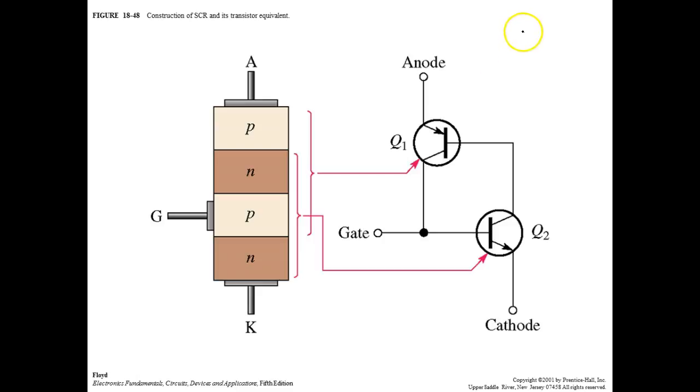So if I put my load, a resistor right now, and put my SCR right here, and then make this common, then this up here would have to be positive, right? Y'all understand that? Or if I made the cathode negative, then the anode could be negative, but it's just got to be negative in respect to it. So once we forward bias this thing,